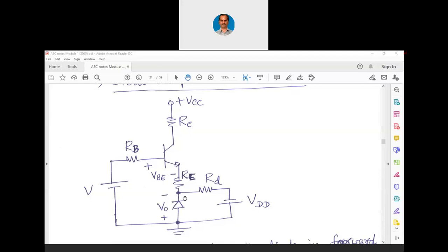So what actually happens here is, if this base to emitter's VBE changes, accordingly in the other direction, the drop across the diode also changes. That way they compensate each other. I hope you got this point now. The diode at base to emitter and the diode which is connected below, they are in opposite direction. But current keeps flowing because the diode at the bottom is forward biased by a separate power supply.